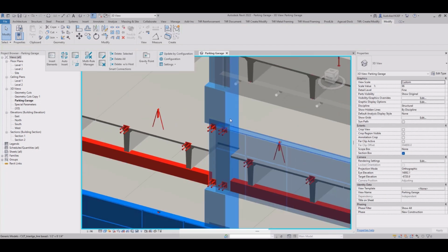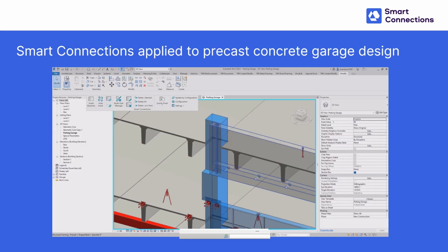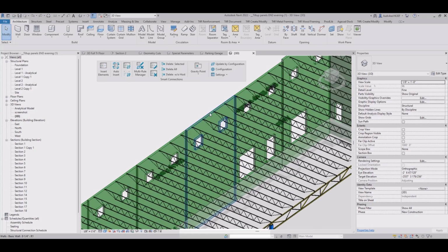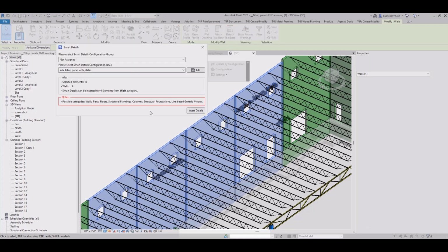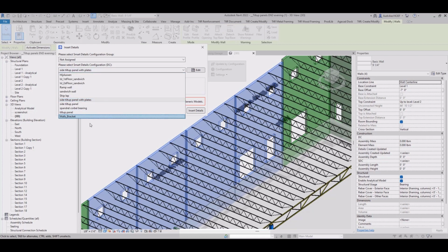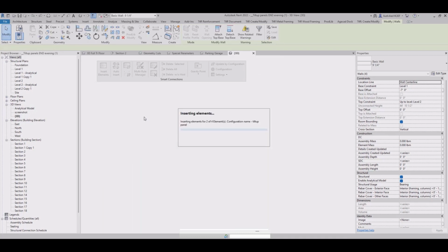Okay, another scenario is with these tilt-up panels. Like for this example, we have lots of web joists, and I want that where there is an intersection. Alright, so now I'm picking configurations again, what kind of elements I want to have in my tilt-up panels, and I want to have a connection right where I have an intersection of my web joist into the tilt-up panel.